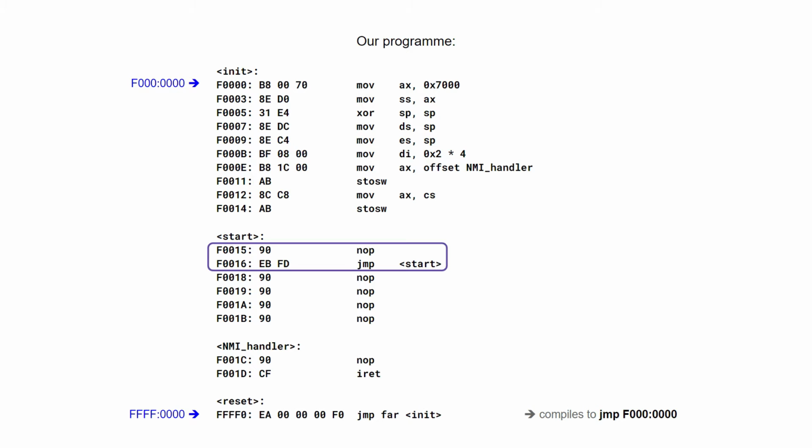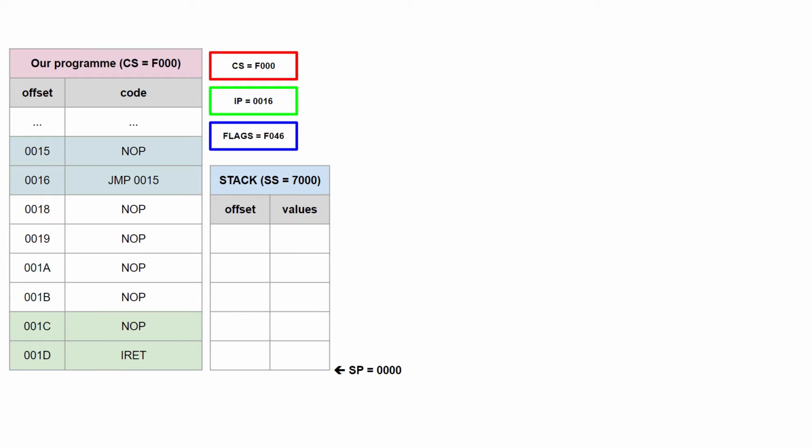You may ask why I spent so much time talking about the stack before testing how our processor handles interrupts. Well, interrupts, as the name suggests, interrupt executing the regular program when they happen, and the CPU before handling them needs to store the place in the program where it got interrupted to carry on after. Just like calling a subroutine, but it may happen at any moment, not as a result of executing the call instruction. To be precise, there is one more difference.